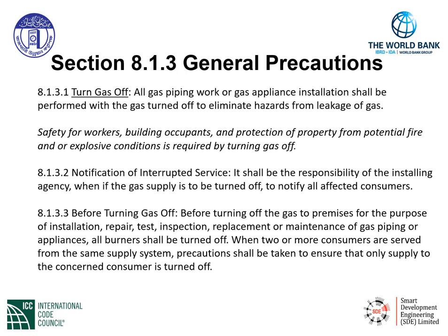And when we relieve the pressure, we want to make sure that we relieve it somewhere to the outside of the building, never inside of the building, because that could create a mixture of gas leaking into the building, mixing with air, and it could be potentially damaging. We need to protect the property as well from potential fire and maybe explosive conditions. So that's why this section is in our code, because it is safety, and it is required for anybody working on the gas system to turn the gas completely off.